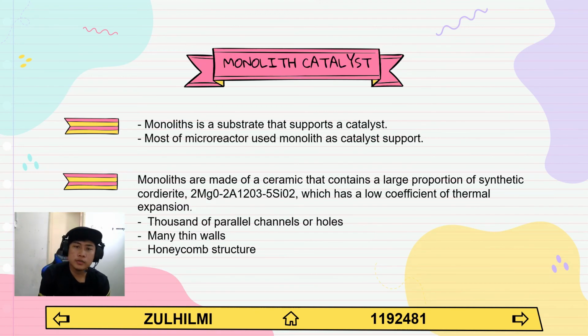So next, we move on to monolith catalyst. What is a monolith? A monolith is a substrate that supports a catalyst. Most microreactors use monoliths as catalyst support. Monoliths are made of a ceramic that contains a large proportion of synthetic cordierite, which has a low coefficient of thermal expansion. The properties of a monolith are that it has thousands of parallel channels or holes, many thin walls, and the structure is honeycomb.